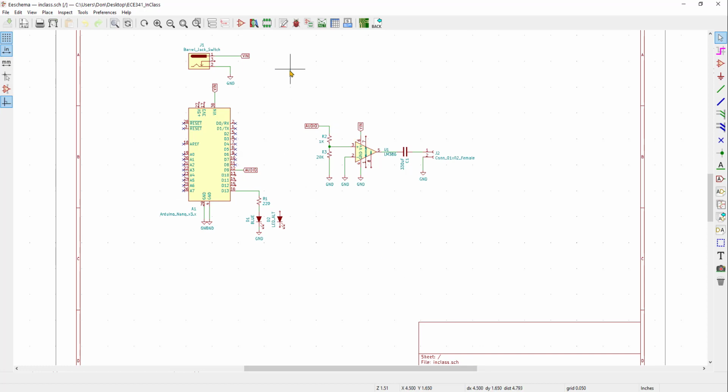The other thing that we're going to see here that's pretty useful is I use this concept of connected nets. So most schematic tools have the ability that if you have a named net, in this case VIN, it'll be logically connected to every other spot that's labeled VIN. So here's another spot and a third spot. Similarly, we can connect signals, and in the case of ground, most software tools also have the ability to put a very specific shape down, and that shape will connect. This really makes it a much nicer layout rather than drawing wires every which way.